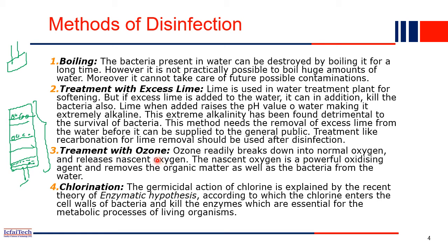This is a very effective treatment method. When ozone comes in contact with the water, it decomposes, and ozone will readily break down into normal oxygen and release what we call activated oxygen. This activated oxygen is a powerful oxidizing agent and removes the organic matter present in the water, that is, the virus and bacteria present in the water. So ozone is very good for treating water for disinfection purposes.